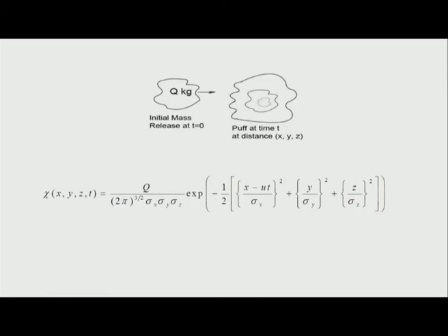Now, the last point which I want to cover in this release is, we talked in terms of a puff being released in a medium in which there is no wind. Now, supposing I release q kg at time t equal to 0 and you have a wind direction. Therefore, what is it I have? I am talking of my release with respect to the wind. Therefore, in the frame of reference of the wind, my x direction is x minus ut, and therefore I just modify x.